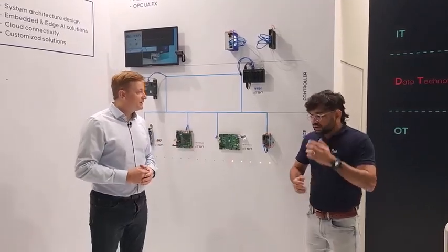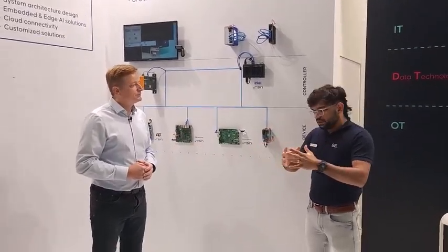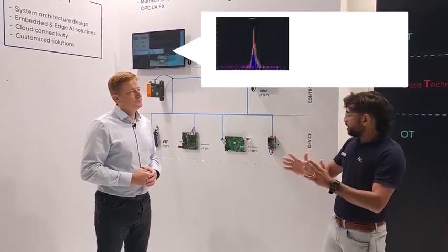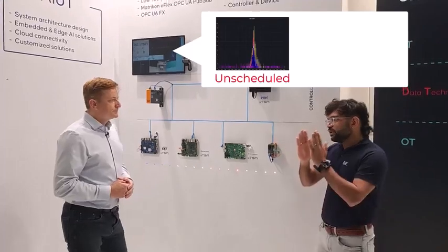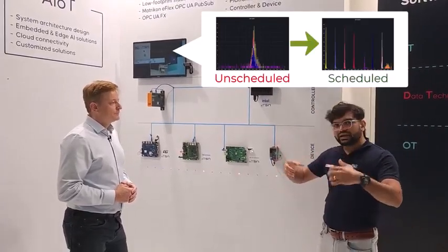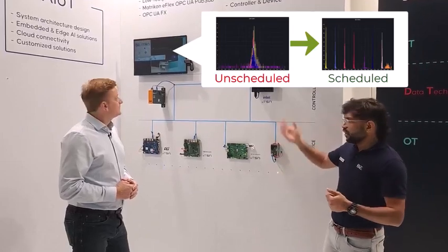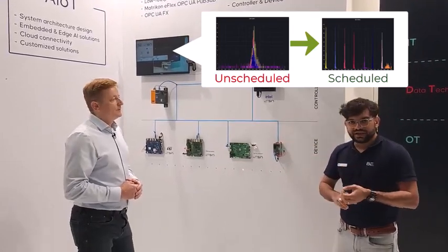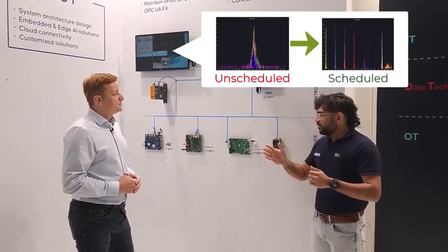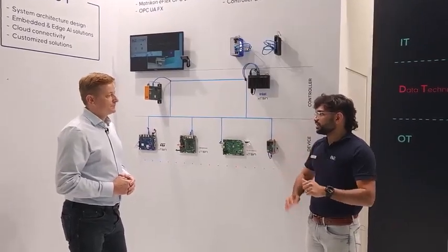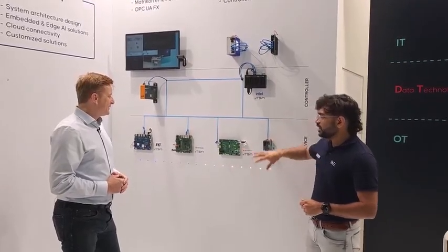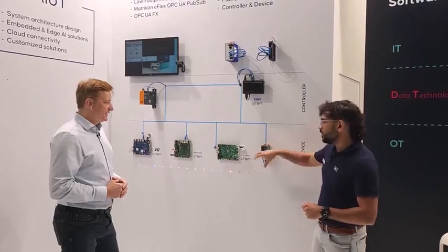Imagine you have a bandwidth of 10 Gbps, then we are going to say that the isochronous traffic, which is hard real-time traffic, will not be disturbed at any point of time, and we can allocate the rest of the bandwidth for other traffic like audio, video, voice over IP, configuration data, and things that are non-critical. Imagine this is something like your airbag data always comes in, but your music data will take some time. We don't want people to die. So these are time-critical systems that are being demonstrated here.